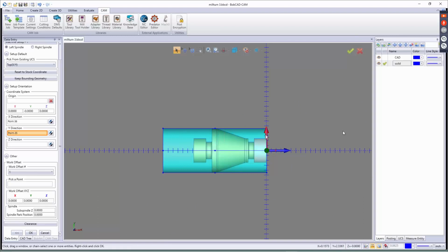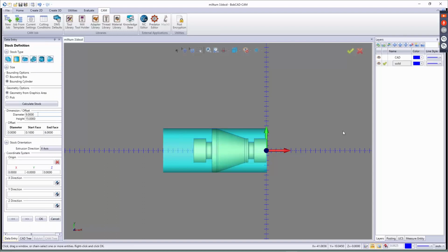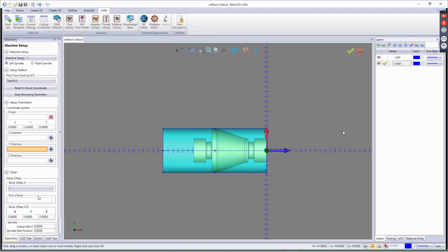for turning and milling for the mill turn, is actually our chuck is right here on XYZ0. So we kind of got to move this out, let's say Z right here. And we're not worried about the spindle and park position because we're not working with a secondary spindle or doing any part transfers. So I don't even remember how wide this part is. If I go back 1 page here, I got 9 plus 6, that's 15 it looks like.